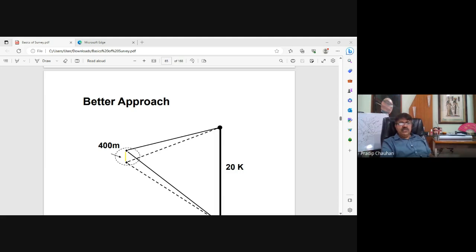You have to line out that particular foundation. You have to prepare 4 side pegs to ensure that those pegs are not removed during earthwork, because every time you have to take the center for preparation of the foundation, column, beam, everything. You have to maintain that. So this is all about survey.